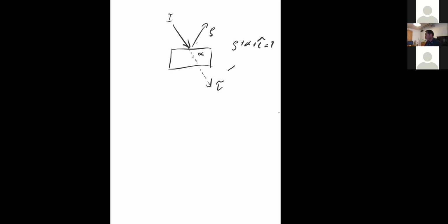That's the normal thing. And now if the whole thing is in equilibrium, what's absorbed in here needs also to go somewhere. So either the whole thing warms up, so it's getting the energy inside, or it's emitted again. So if it's emitted, then you get an epsilon, emittance coefficient. And if you think about it, if it's in equilibrium, as much as it is absorbed should also be emitted. So that's why the emission coefficient is usually the same as the absorption coefficient. So if you get a 100% absorbing thing, then it's also 100% emitting.